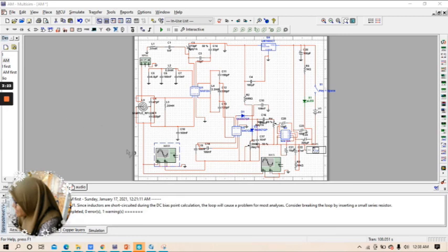The local oscillator, which is tuned to the station frequency, is also designed to have a reception bandwidth from 550 kHz to 1700 kHz. The IF amplifier then amplifies only the signal equal to the intermediate frequency, followed by the limiter, the FM detector, and the AF preamplifier. The output from the last stage, which is pin 7, is fed into the audio section, and finally to the speaker.